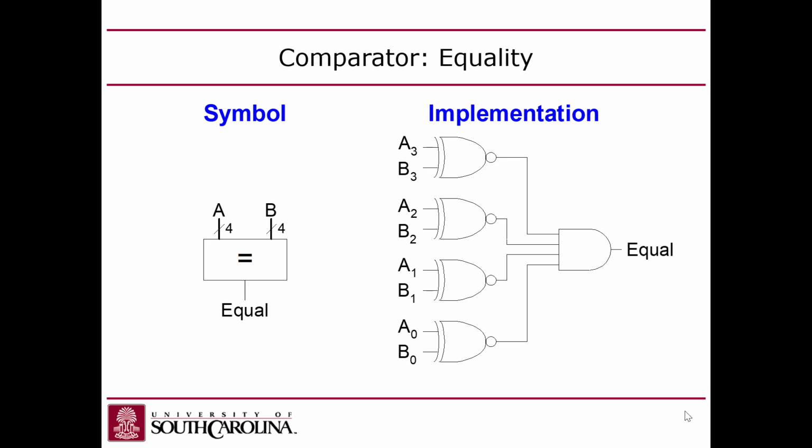If there are more than 2 inputs, then it's like a parity operation. But if you take the 2 input XOR of each of the corresponding bits in two multi-bit values, then there'll be a 1 in all the bit positions where they differ. If you use XNOR, then you'll have a 1 in all the bit positions where they're similar.